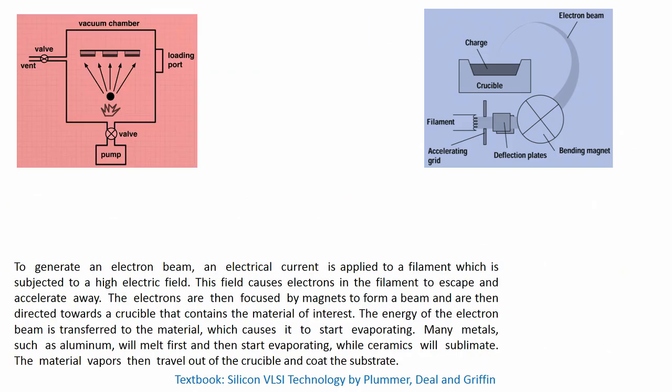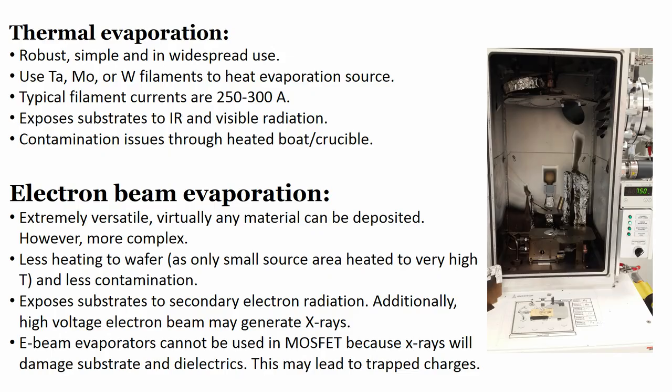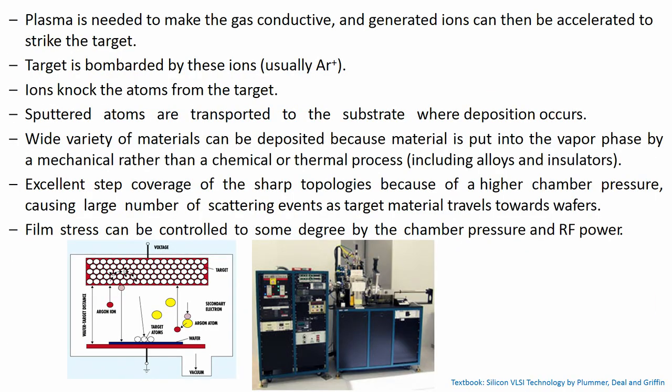Let us see how sputtering will look. We have seen thermal evaporation and e-beam evaporation, and what is there within the chamber. Let us see sputtering. In this slide, you see the target, which is your source, and you apply the voltage between the anode and cathode, and in the bottom you load your wafer.